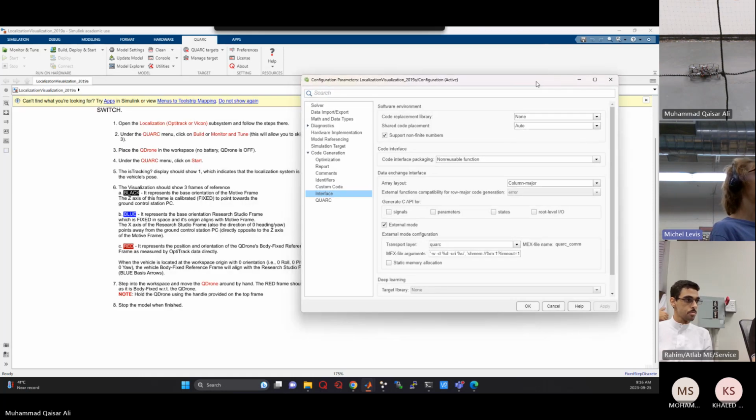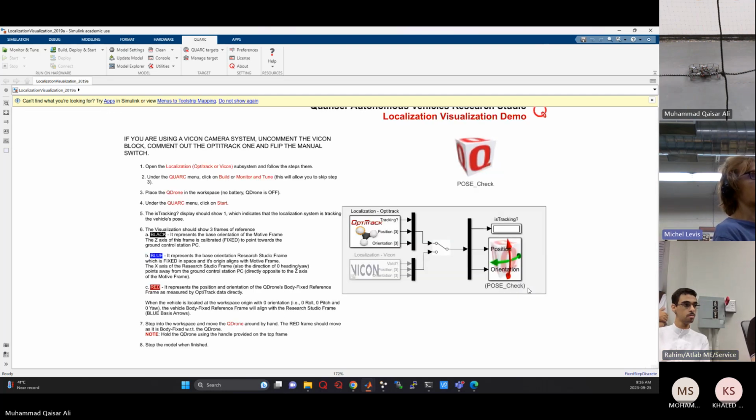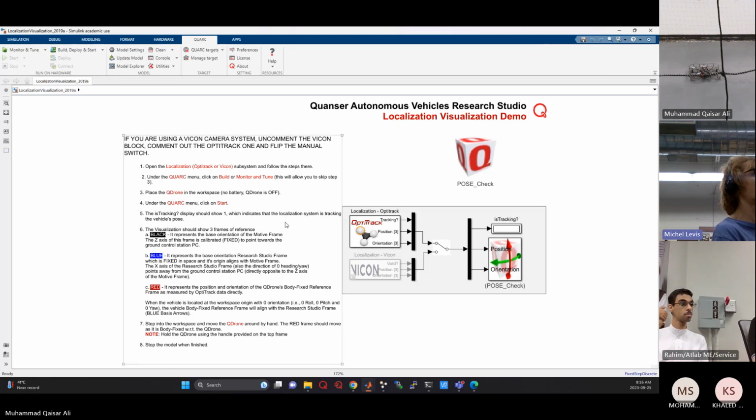So what you do here, you don't need to remember this is running on your host. It's running on your PC, because your cameras are connected to your computer. So no need for that. But what you do need to do is define the new files that you just created. You have a new calibration file, you have a new rigid body.